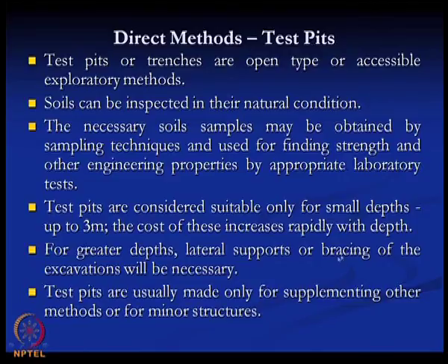Now, for greater depth, lateral support or bracing of the excavation will be necessary. So lateral support or bracing system will be necessary if the depth is high, and the cost will increase rapidly for a higher depth. So test pits are usually made only for supplementing other methods or for minor structures.